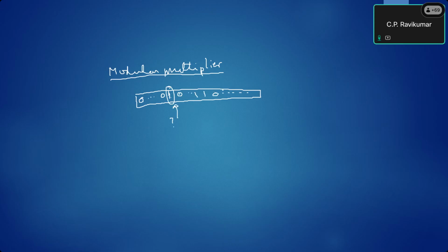We have a big number, and we want to find the leftmost index which has a 1 in this position. In our implementation, we use the while loop. If you build hardware also, in the same way it will work. The hardware will possibly have to do the same thing. It could be a small state machine that reads these bits one by one.